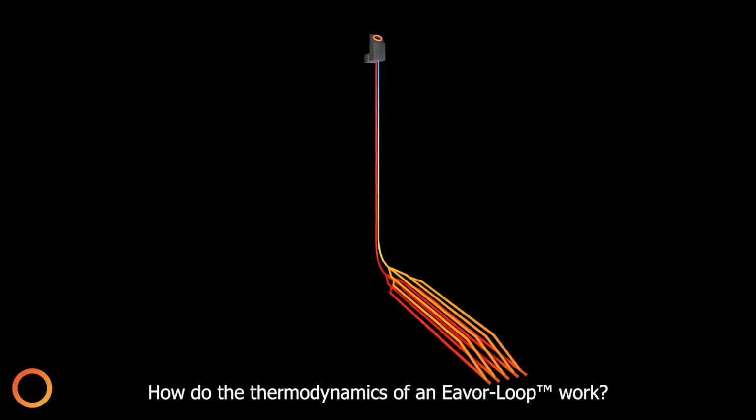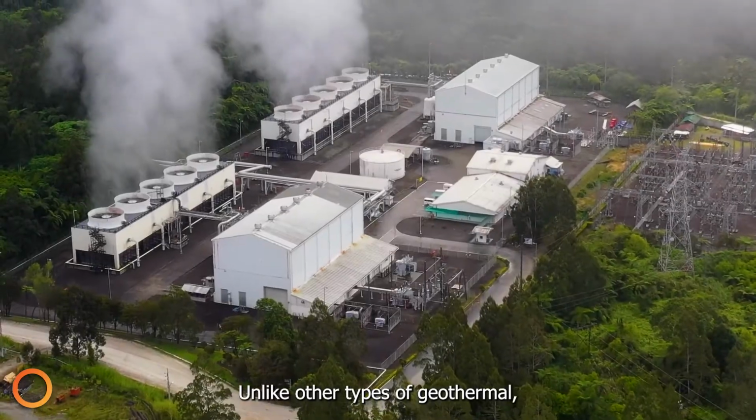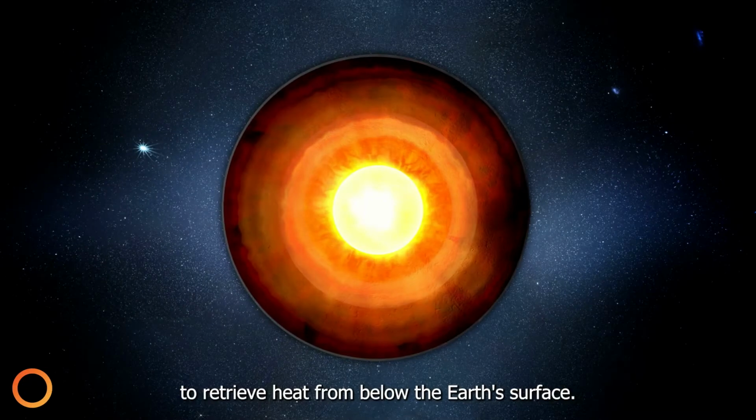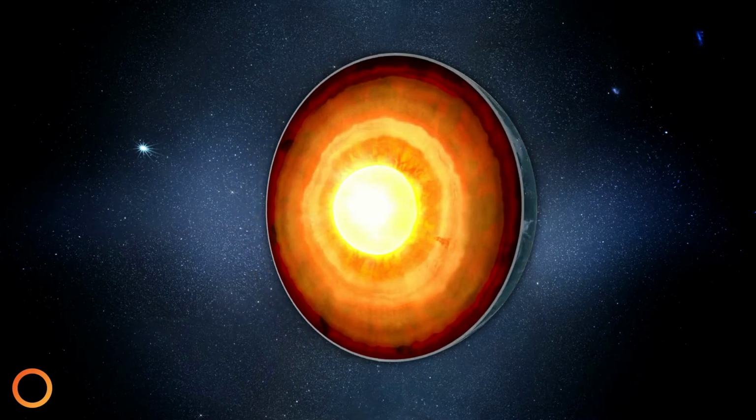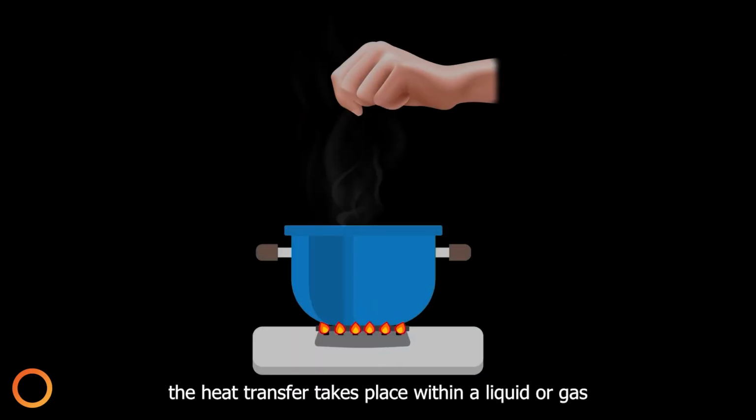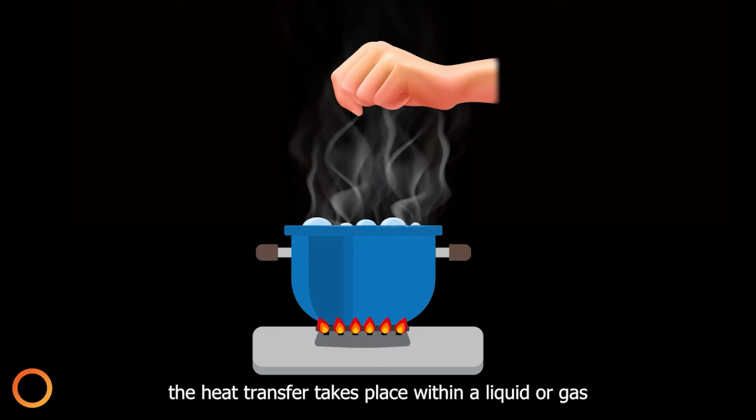How do the thermodynamics of an Eavor-Loop work? Unlike other types of geothermal, the Eavor-Loop uses conduction instead of convection to retrieve heat from below the Earth's surface. With conduction, heat transfer takes place between mediums by direct contact. In convection, the heat transfer takes place within a liquid or gas that's in transit.